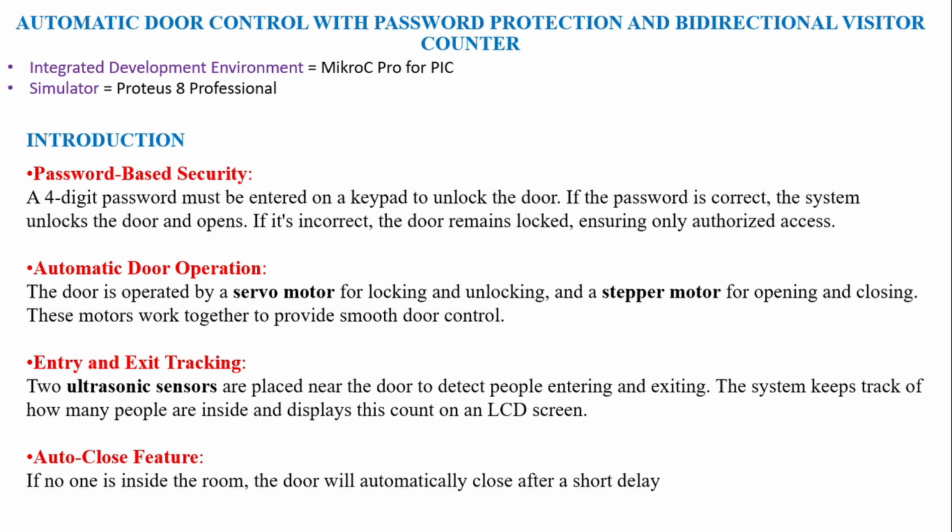Automatic door operation. In this, we use two motors: a servo motor and a stepper motor for smooth operation of the door. The servo motor is used for locking and unlocking of the door, and the stepper motor is used for opening and closing of the door.